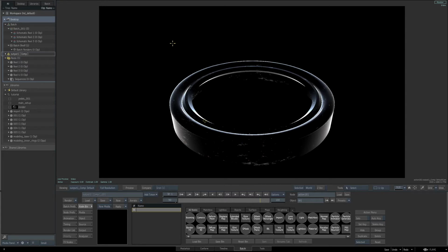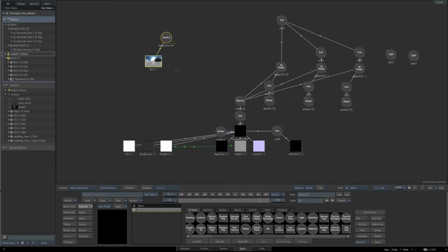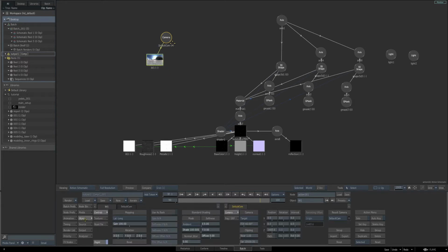But we want to change this to look more like studio lights being cast down onto the objects. And we want to change the texture a little bit. For the IBL, this is the default texture, but we want to change that. Down in the parameters with objects selected, go to the read file. You'll see the load button that's available for the texture that's being used. Also, we can create our own in batch.